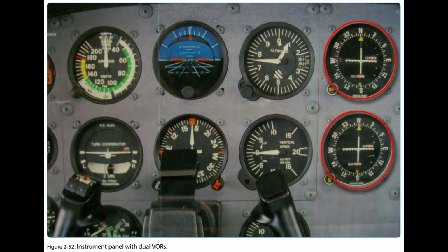3. Prior to takeoff, ensure that the RNAV system is available. If possible, check to see that the system is updating when aircraft position is changing. Note, while in flight, continue to verify system accuracy by displaying bearing/range to a VOR/DME on the RNAV system and compare it to the actual RMI reading of that particular navaid.